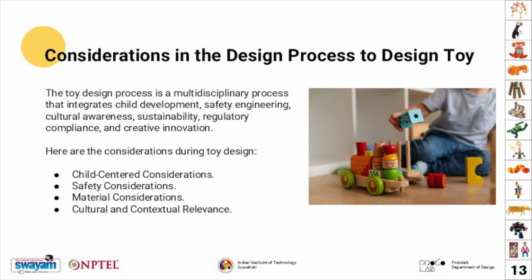Safety considerations remain the primary principle in toy design. Toys must have no sharp edges or small detachable parts that pose choking hazards. Material must be non-toxic and compliant with standards such as IS 9873, EN 71, or ASTM F963. Electrical safety and flammability resistance are equally critical where applicable.